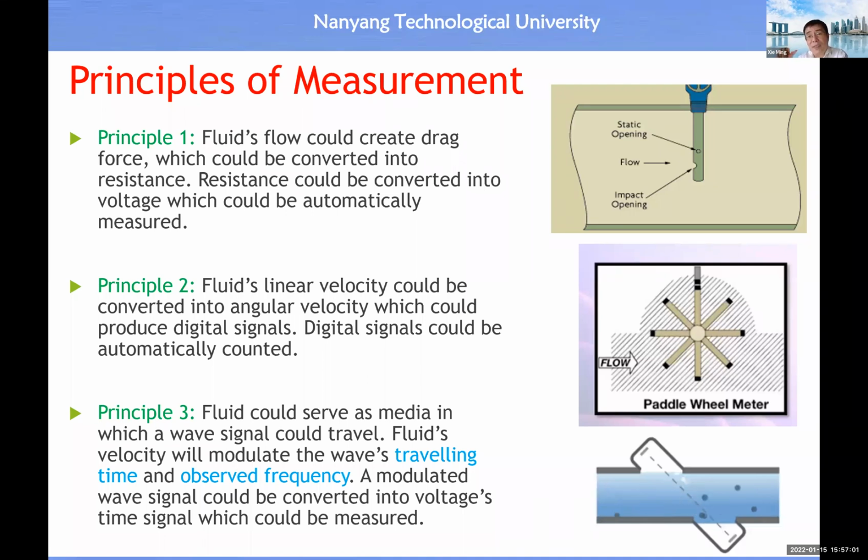We apply a time function of a voltage, then produce a sine function of a wave. When this wave travels through the fluid and reaches the detector, the sensor, actually the sensor, the piezoelectric material, will directly convert the wave or the pressure wave into a time function of a voltage, all right? So the actual implementation is quite straightforward.